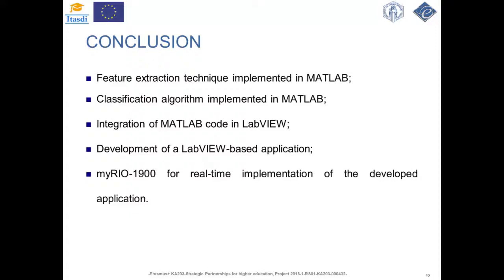It was pointed out that if this node is used, there is a need of a MATLAB installation on the computer where the program is planned to run, because if there is no MATLAB installation, there will be an error and the program will not be able to run, because in the background the MATLAB script node opens a MATLAB command window.